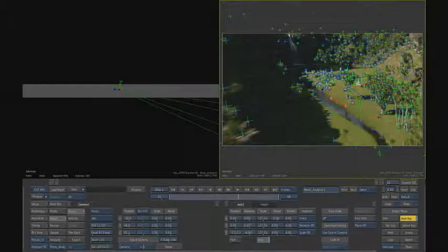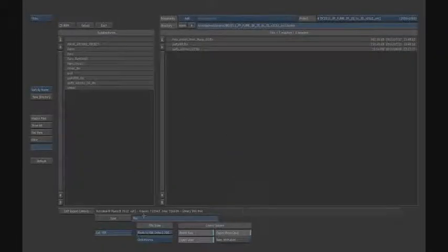So we could decide that we think this is approximately 5 meters in size. So we'll set an overall scale here, and then when we go to output our camera, we're going to export this camera with the point cloud and set our scale in meters with a scene value of 1.